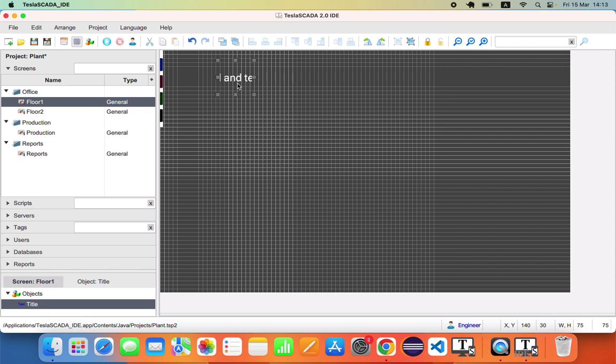Use the up, down, right, left arrows on your keyboard to move an object. If you turn on caps lock, you can use arrows on the keyboard to change the size of the object. You can also set the location of the object in the properties.